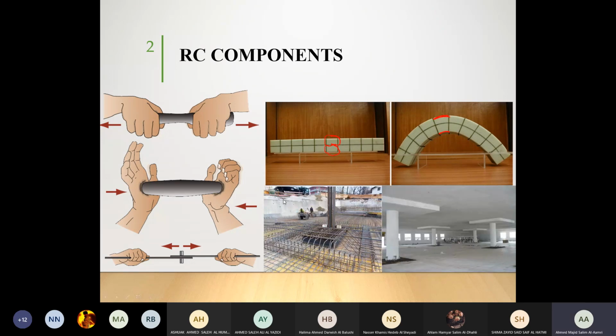For shear, to avoid shear failures, we normally supply different solutions. Like here, they are supplying steel plate. I don't know if you'll be able to see it or not. Or we can apply something like a cap. We call it a drop panel or a column cap. These are supplied in flat slab system. We are going to see it further, but this is a solution to the problem of shear.